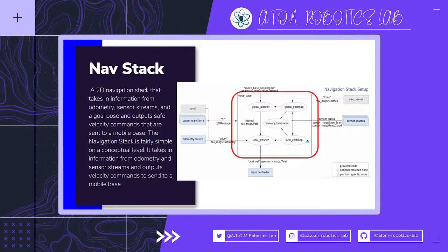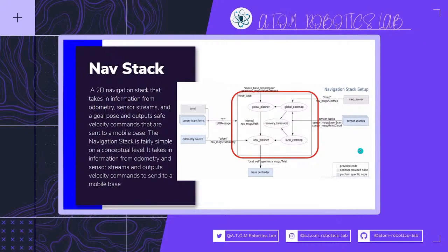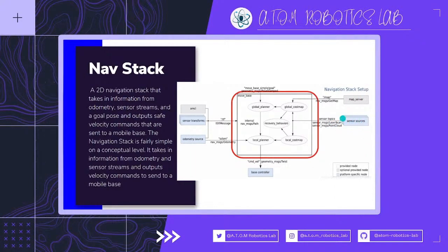Recovery behavior is for when the bot gets lost. The bot takes a 360-degree turn, sees its surroundings, and relocates itself to where it actually is in the odom. So this is how the navigation stack works, and it takes data from sensor topics, like the lidar. So this is the navigation stack.